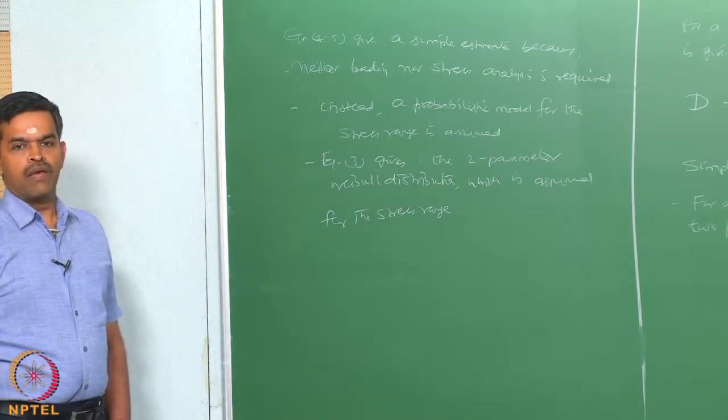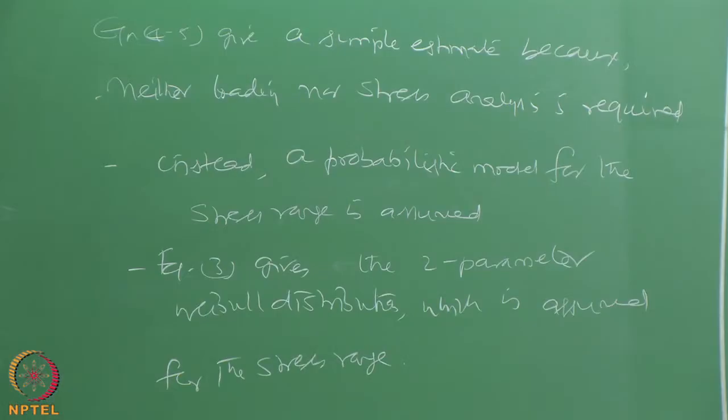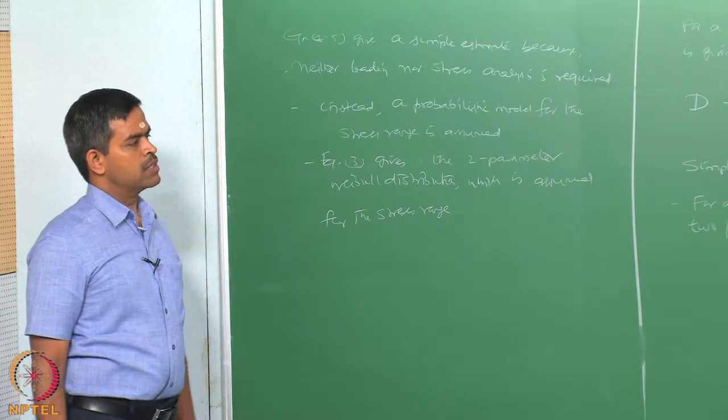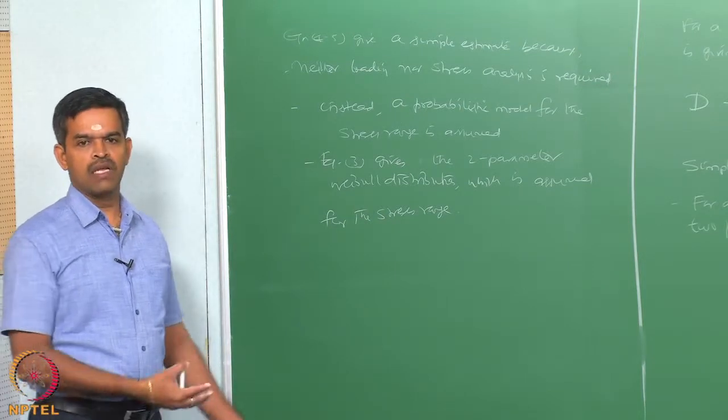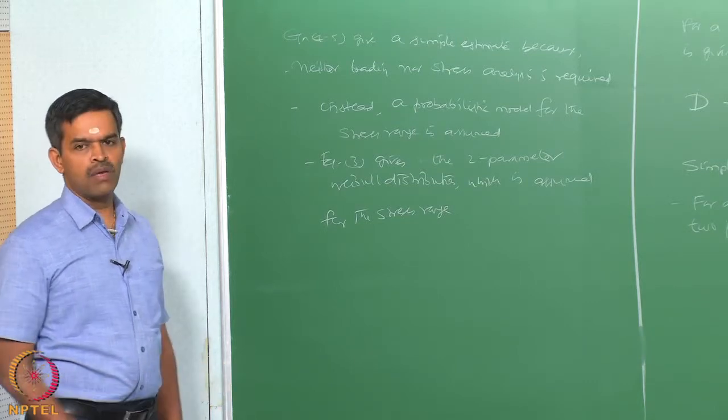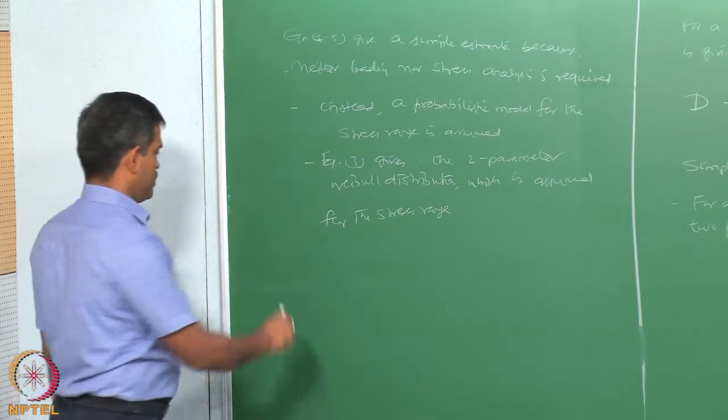Now, fatigue life estimates calculated from the above equation may actually vary from those expressions we gave in the earlier lectures, because they will be influenced by what is called a shape parameter.